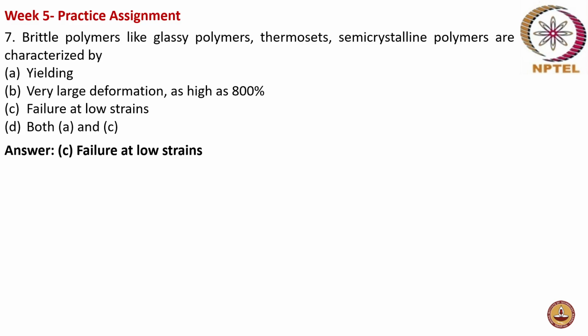But once it reaches its break point, it breaks. That's it. It doesn't yield, there's no change in structure. It will be a kind of catastrophic break. Yielding is a property of a ductile material. There are microstructural changes so that it further takes up load, but not as high a stress as the initial part.